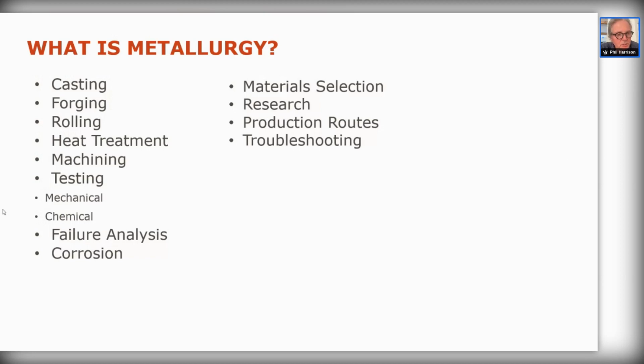It has porosity in there, micro porosity and macro porosity. By hot working, any unoxidized pores are actually healed up, in essence, densifying the material. So the hot working process could be, for example, forging, where we're using a hammer, or rolling, where it could be rolling bars, sheet, or plate.